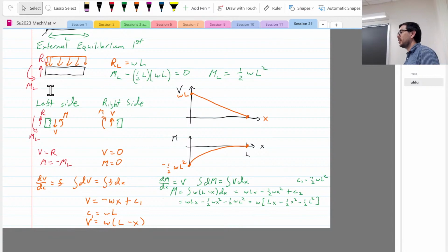I don't know if I should say anything, but session 10 also emphasized indeterminacy and also emphasized angle of twist. We're focusing mostly, I mean, it's possible, but we're focusing more on the stresses in this part of the class. Now, do you need to know how to use compatibility to figure out stresses sometimes? Absolutely, because you can't figure out what the internal moments or the forces might be if you have an overconstrained problem.